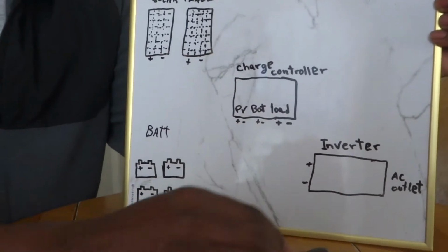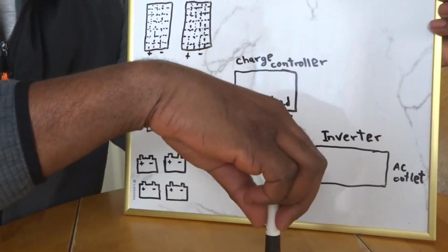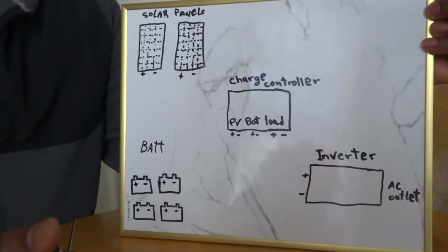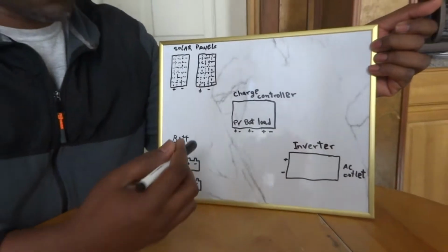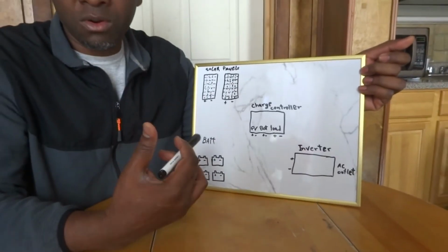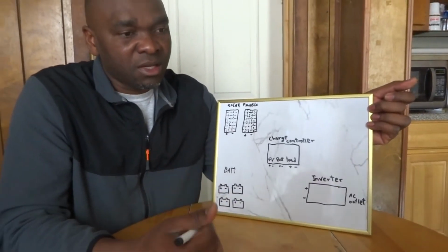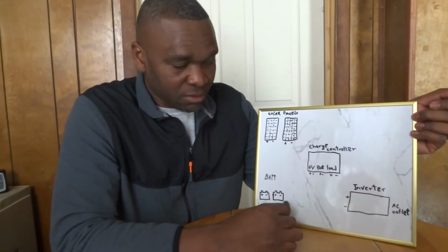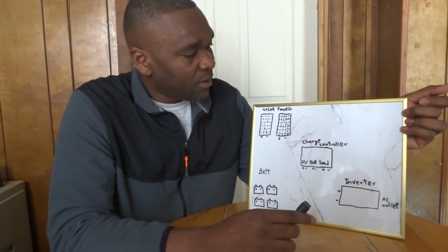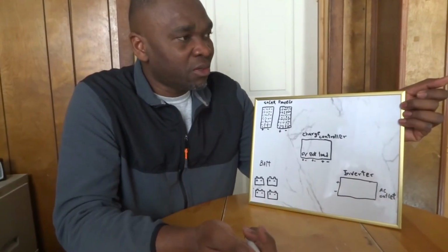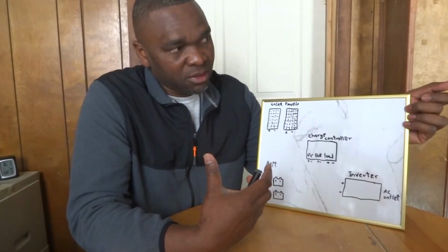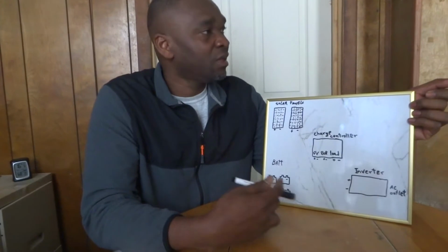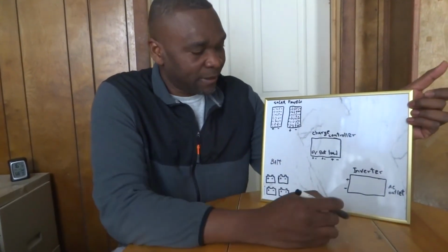And then they have specific batteries for DC, and specific batteries for inverters, which are a little different from car batteries, because most inverter batteries have more capacity in terms of saving energy. And yeah, some people use car batteries for their solar system, but it's not gonna last long, because car batteries weren't built to be charged over and over and then discharged that often.